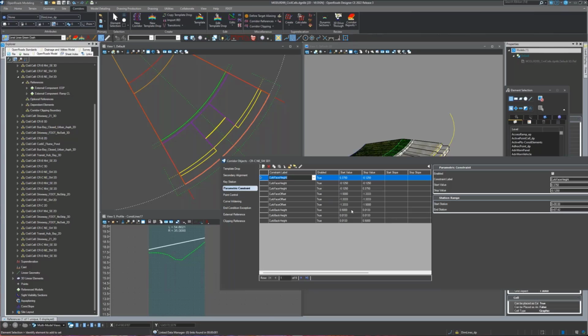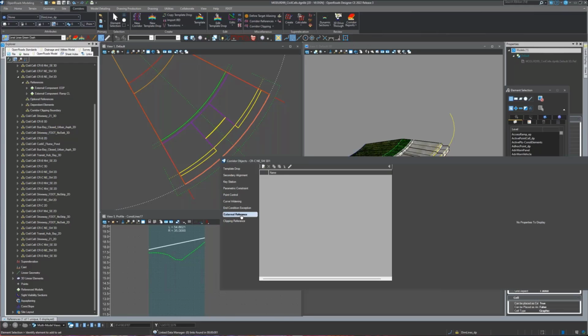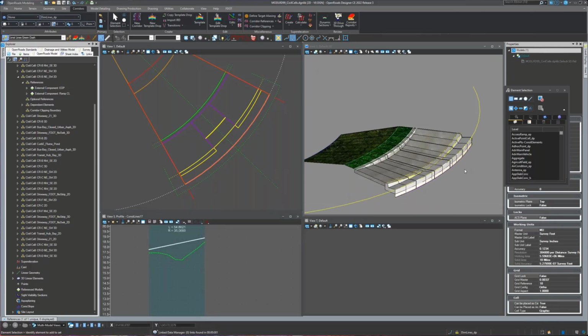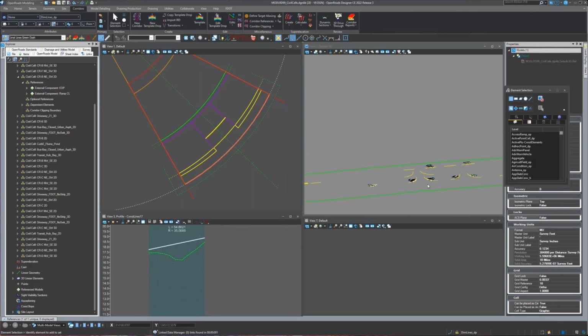And then our curb back height right here is exactly what I was just saying, where we're at 0.5 and then down to that 0.0133, which is 0.02 times 8 inches. And then we're down there through the curb opening, or the ramp, and then back up. I don't think there are external references for this one because it's pretty straightforward. So that one's probably the easiest one.